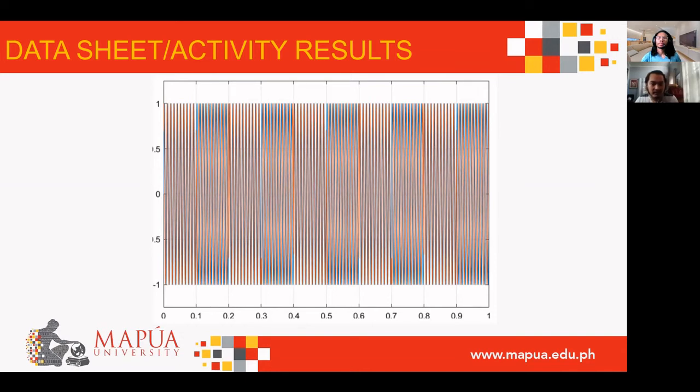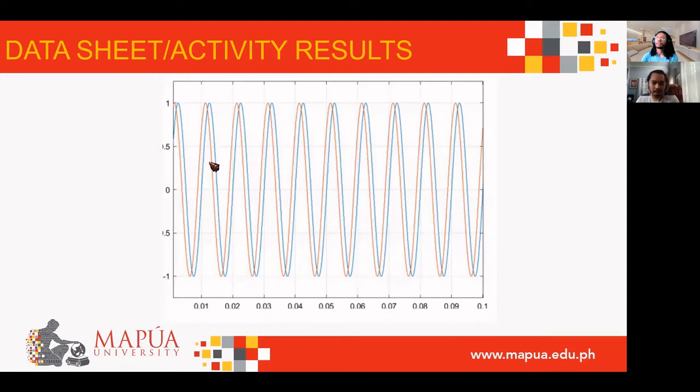So as we can see, although it is not zoomed in, the reference sine wave signal is not in phase with the QPSK signal. Next, moving on, we also observed that there is a pattern in the 2-bit code, which is 11, 01, 10 and 00. This can be attributed to the different periods set in the pulse generators.